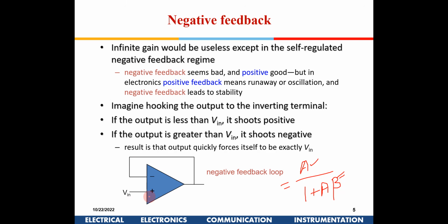Can you repeat, sir? Buffer. If the same input is available at the output, buffer. Yeah, correct. It works as a buffer, sir. It will work as a buffer because the load will be driven by this amplifier from the power supplies, whatever is available, if you connect a load here.